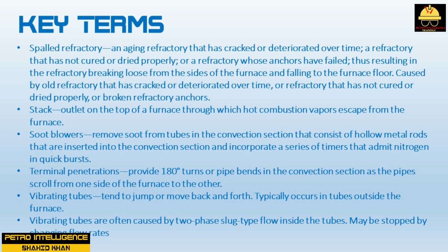Caused by old refractory that has cracked or deteriorated over time, or refractory that has not cured or dried properly, or broken refractory anchors. Stack is the outlet on the top of a furnace through which hot combustion vapors escape from the furnace. Soot blowers remove soot from tubes in the convection section and consist of hollow metal rods that are inserted into the convection section and incorporate a series of timers that emit nitrogen in quick bursts. Terminal penetrations provide 180 degree turns or pipe bends in the convection section as the pipes scroll from one side of the furnace to the other.